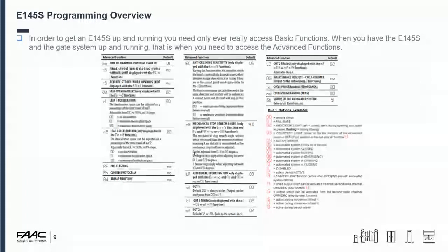So if you're trying to use the encoders for actual safety in that sense on big boarded gates, be wary because that could be problematic. On large boarded gates, I would always recommend the use of safety edges or X guards, laser curtains, if obviously the fitting of safety edges isn't really practical or it's not aesthetically pleasing to the customer.